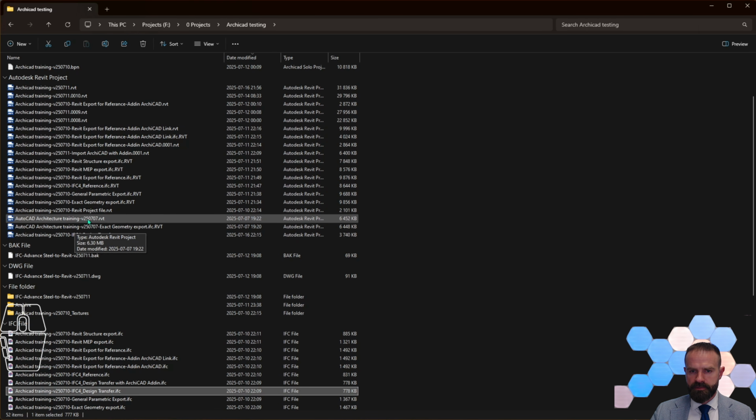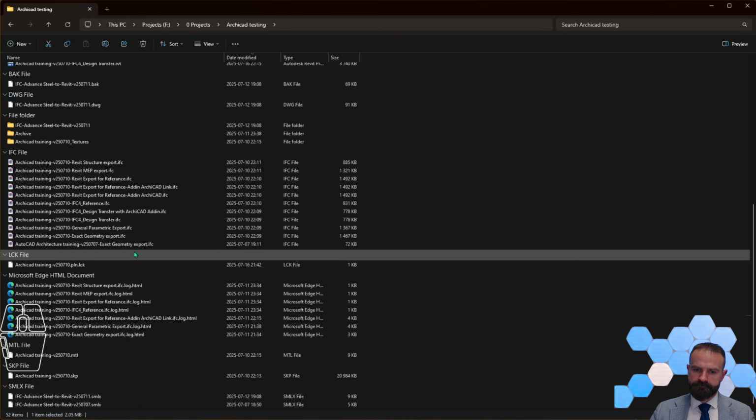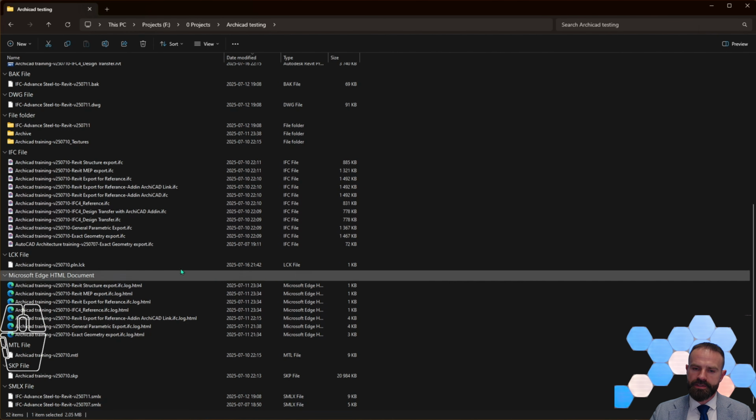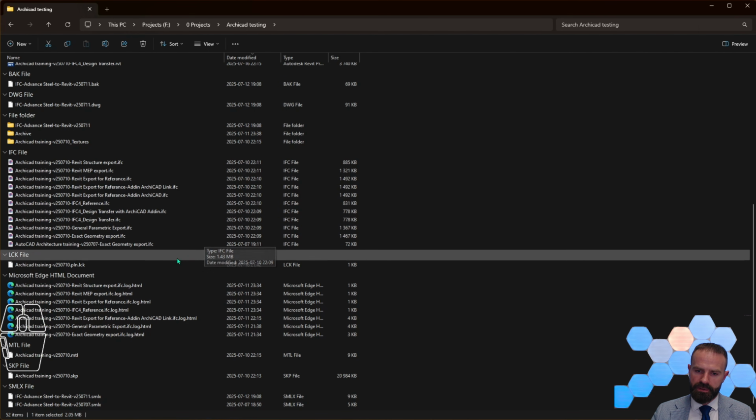So it means Revit project file should be exported from ArchiCAD. So in BIM execution plan, BIM managers should write it down and provide specific workflows how these files can be exchanged from ArchiCAD to the Revit application.